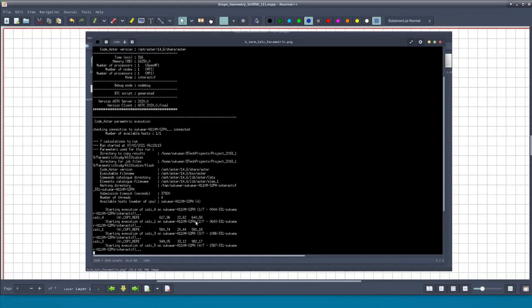Also, we may need to adjust the analysis settings like the maximum number of global iterations and the automatic step downing of time. Those features of Code-Aster need to be adjusted for a particular problem so that we get convergence near the actual factor of safety.